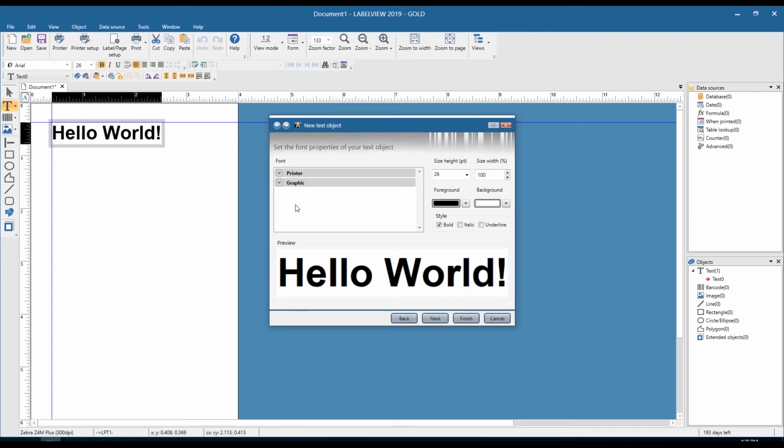So if you start to see things like your printer will print a label and pause, print a label and pause, it's possible that you're overloading the printer's buffer memory because maybe you're doing some huge batch jobs, thousands of labels at a print, 24/7 printing, heavily populated label templates, things like that. And you just cannot have that pause between prints. You'll start to lessen the amount of data going to that printer. And usually one of the first things we'll do is try to switch over from graphical fonts to printer resident fonts.